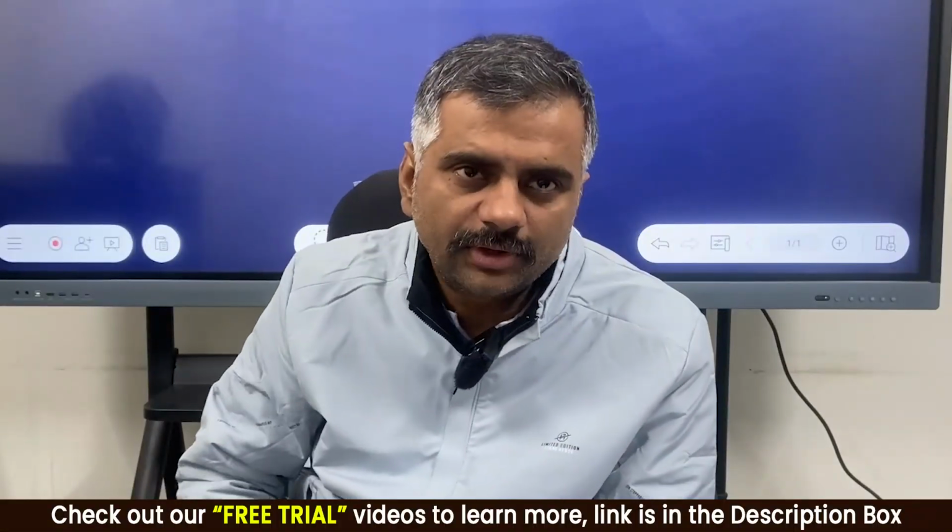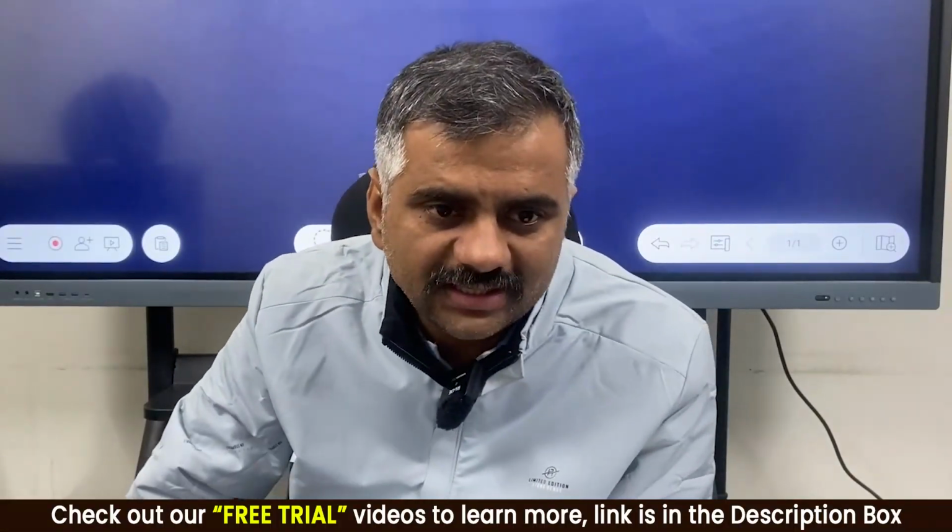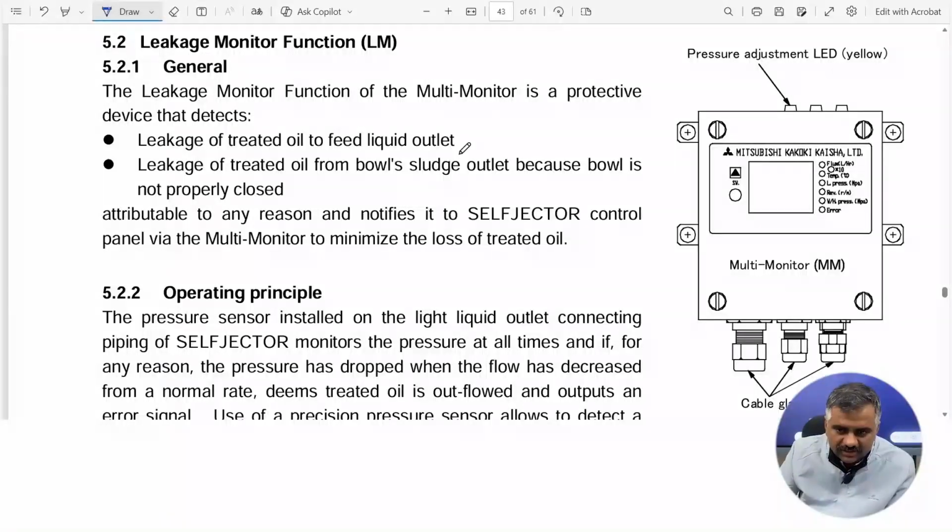Okay, so in this module guys, we are going to study about the leakage monitor function. Leakage monitor function is basically checking for the pressure drop via a pressure sensor in the treated oil outlet line.